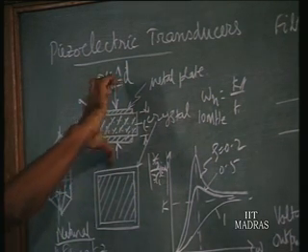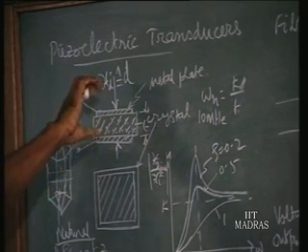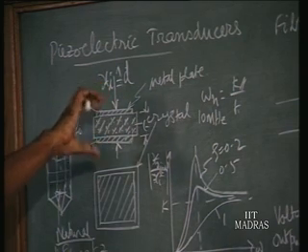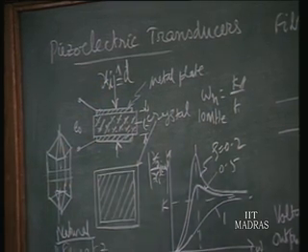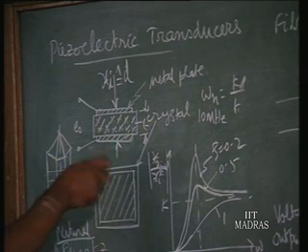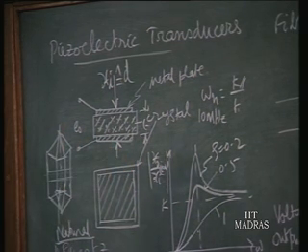So the displacement that we give should be of changing magnitude. That is, it should have a certain frequency. As per our derivation yesterday, the minimum frequency should be 3.04 over tau, where tau is the time constant of the circuit, and beyond that frequency alone you will get the charge here. That is the limitation. Otherwise, this crystal is also made use of for transducing displacement into a voltage.